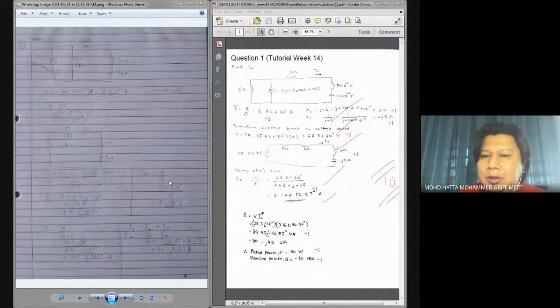All right. Please remember, guys. In order for us to calculate the frequency domain circuit, I mean, when you try to calculate or analyze your circuit, please make sure you convert from this peak value into RMS value. That would reduce the possibility of doing wrong in the next portion of the question.